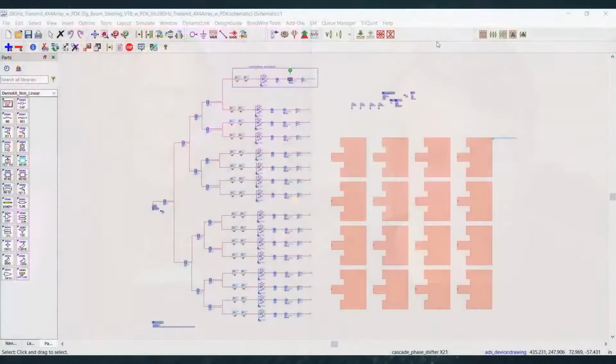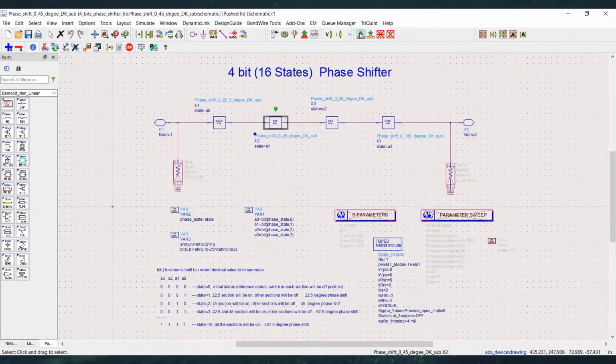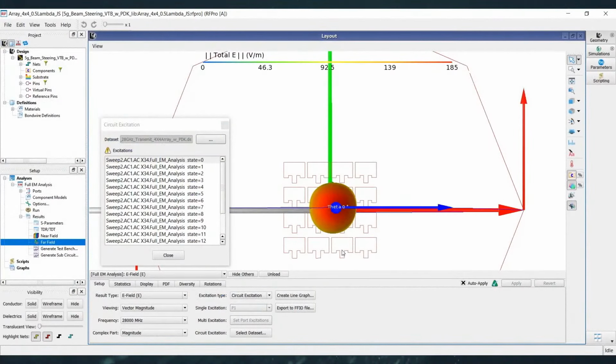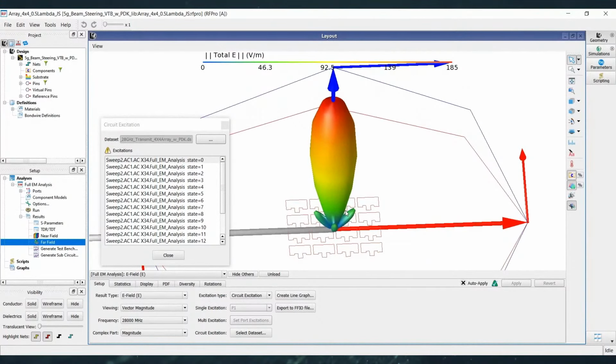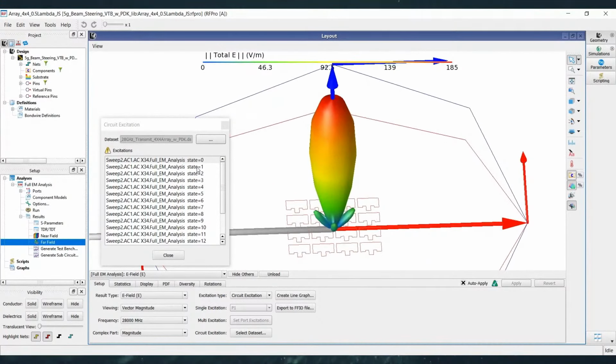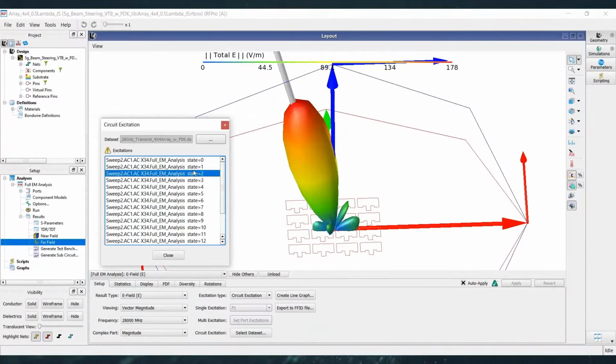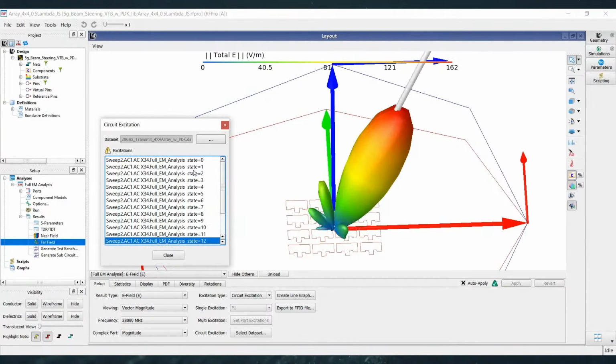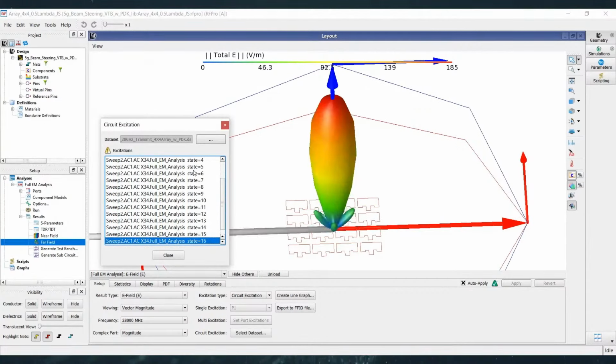One example of that is a technique called modulation distortion, or in simulation we call it distortion EVM, error vector magnitude. It's actually a measurement technique that we're able to apply also to the simulation space. Essentially, if you think about a spectrum, you have a signal coming out, and then you have these sidebands, the noise. On the measurement side, we're able to mathematically separate the original carrier signal from the distortion terms. And in doing that, we can compute EVM without having to use a modulated signal.